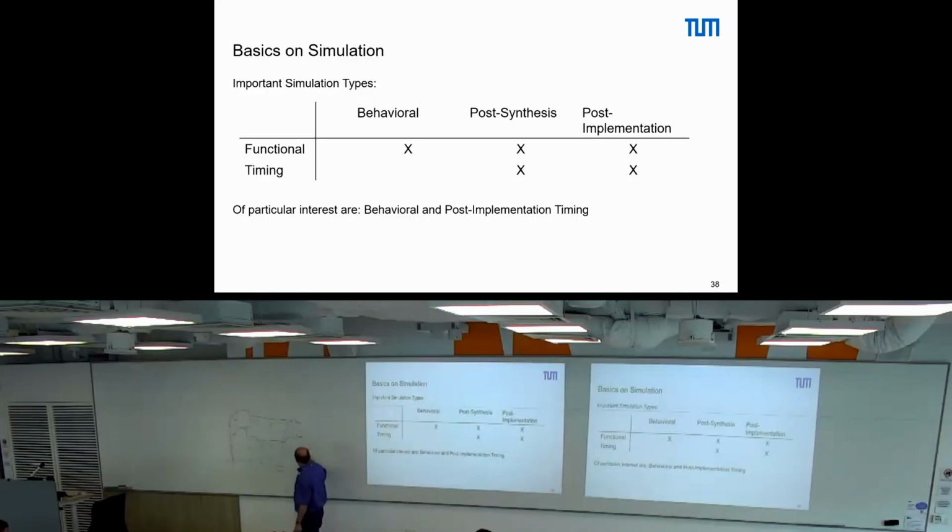The OR is usually a little bit slower than the AND, so we have maybe something between 1 and, let's say, 1.3 nanoseconds. Just to have some numbers in mind. Now, the shortest critical path in this circuit: I just neglect the wires here, because otherwise we just do additional computations, but we can neglect them here.